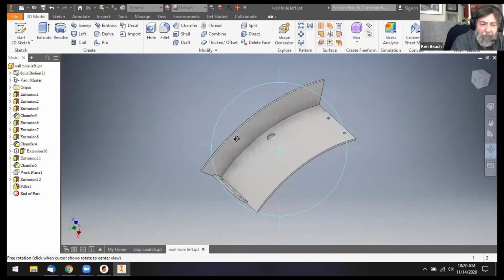And the issue I ran into is, even though my machine supports arcs and everything about it supports arcs, the G code supports arcs, it is not translating my arcs into actual arcs. It's translating it into short straight lines.